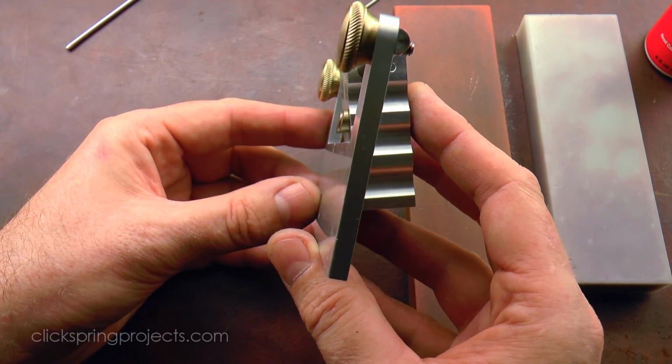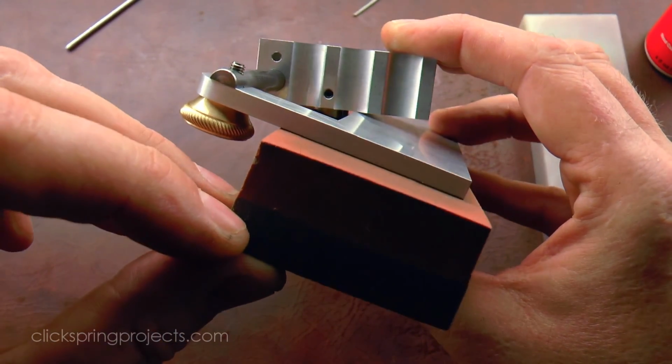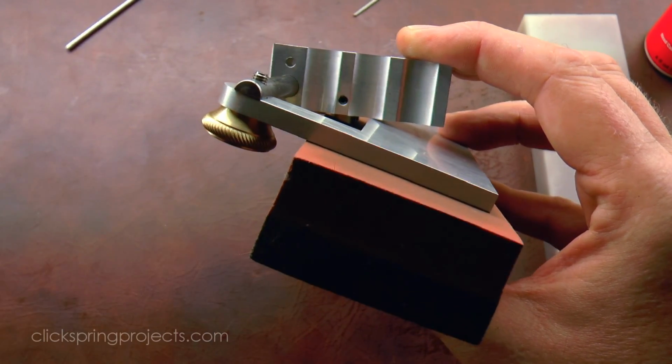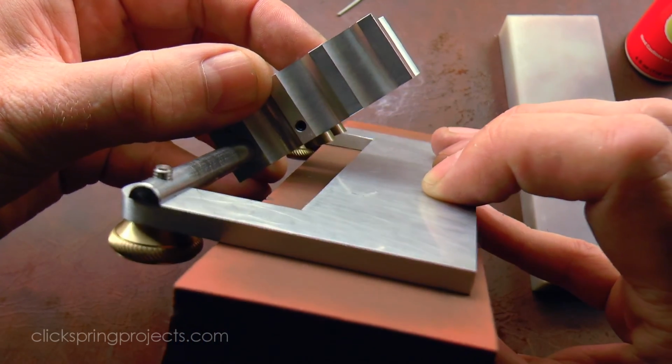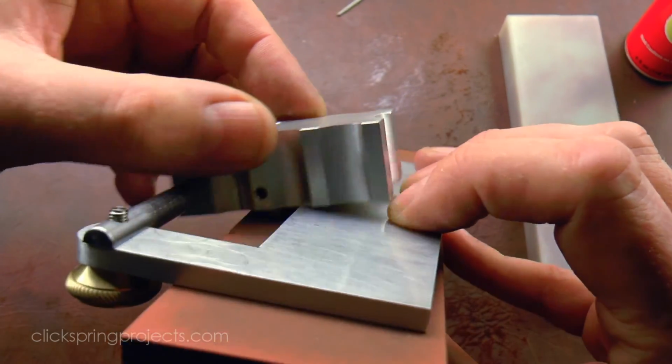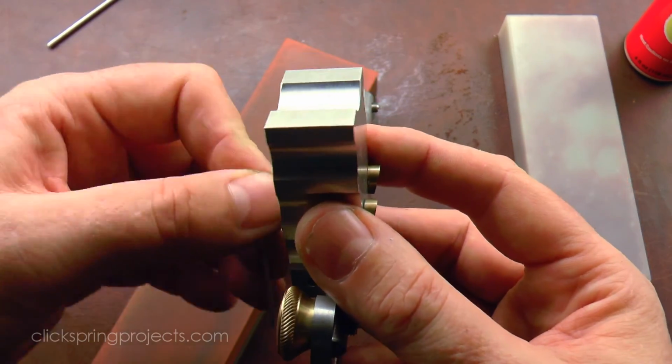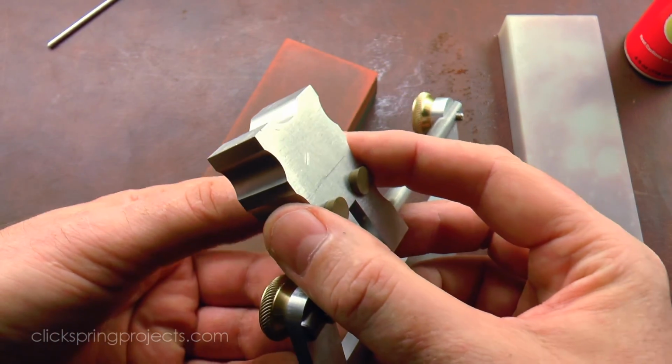The throat dimension of the locating plate has been set to again give an approximation of a 15-degree angle. This acts as a natural stop, so of course to bring the buttons into contact with the stone and give us some material to remove, they need to sit slightly beyond that limit.